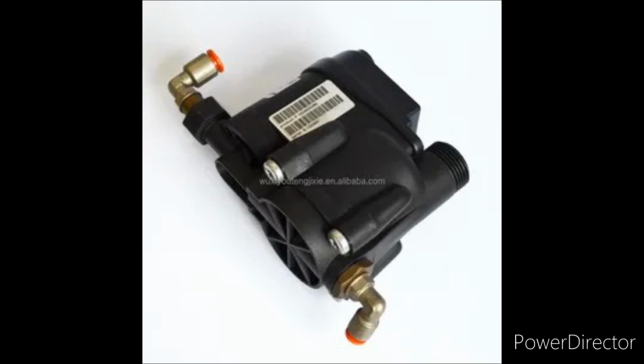Another thing to ensure is that the auto drain valve operates at the same levels as the maximum pressure of your air compressor. Look for anything above 200 psi, and don't forget to pick the right body for the auto drain valve. We highly recommend looking for brass as the body material because it is known to be durable and can withstand high pressure and temperatures. It is also resistant to corrosion.